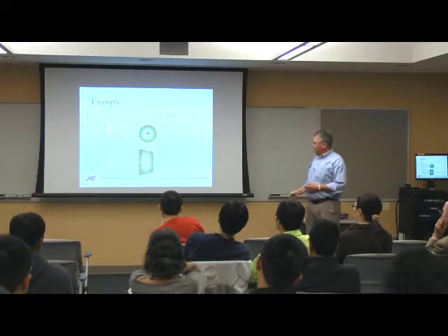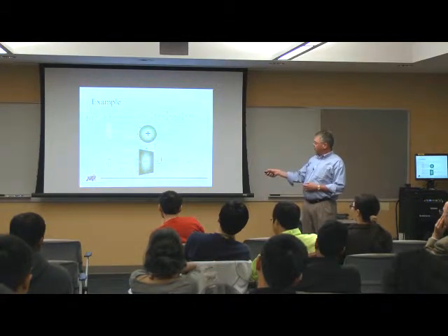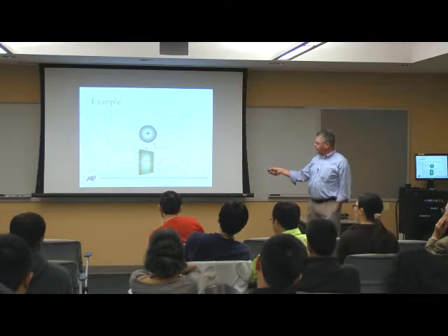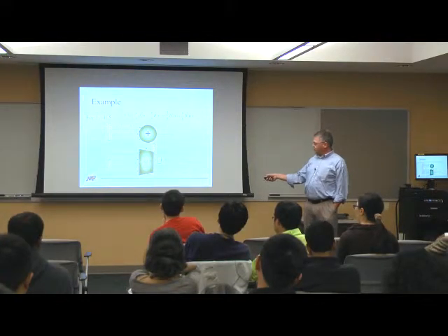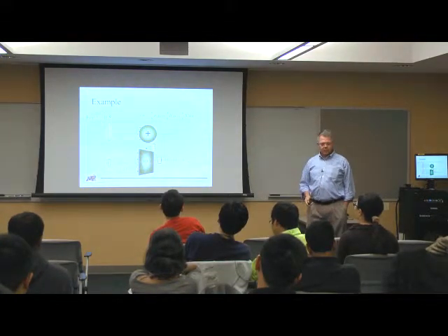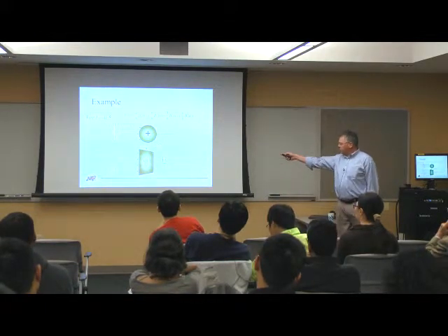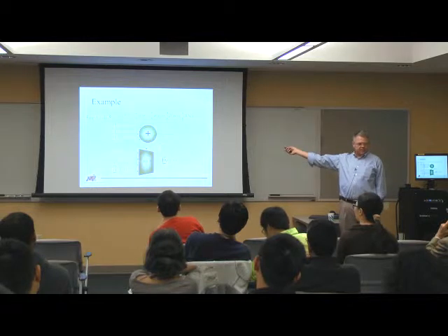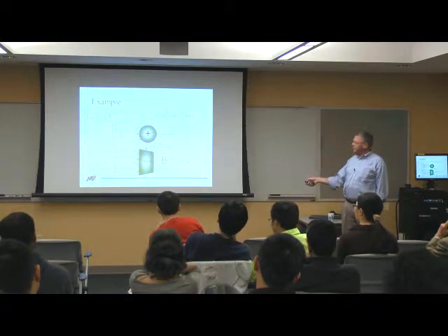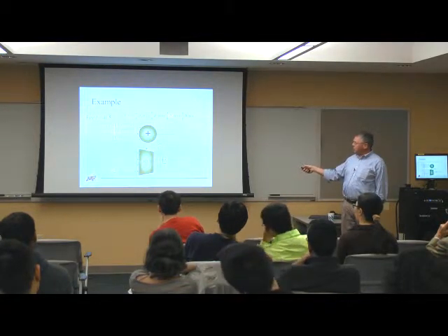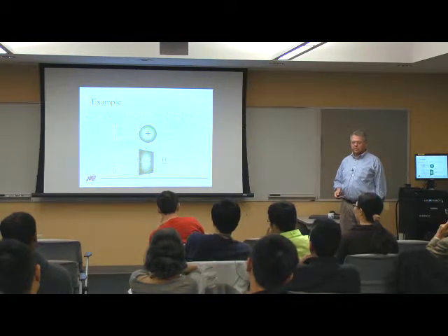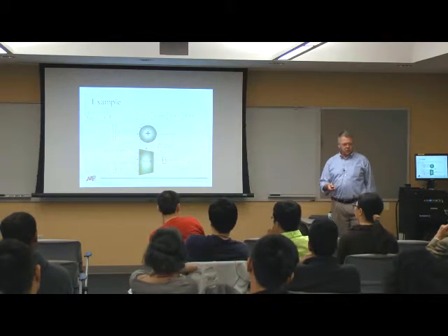Okay? So next cycle, I go here and I have 2 of these inputs that are a 1. I select this second multiplexer input, and that gives me my output there. So I just step through that each cycle, and on average, the output will be, in this case, the value of 4/8, which is the functional value when I have an input of 0.5. Okay? So that's how the circuit works.